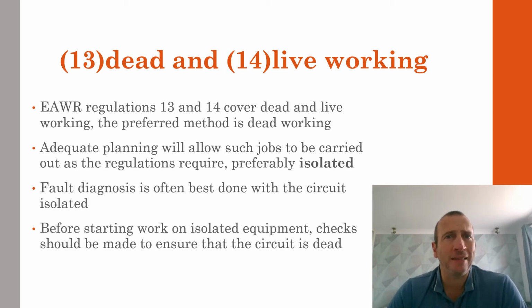Jobs need to be planned so that they are carried out as required by this regulation. Safe isolation is the method recommended in each case. Fault diagnosis particularly is best done when the circuit is isolated. Some electricians may find that working live is faster, and by practicing this method they pass on the bad habit to newer, less experienced electricians. In this case, they are being exposed to a dangerous situation and they are going against the law.